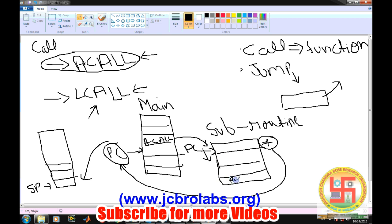And at the end there is a return instruction. In the return instruction, whatever address is stored on the stack is loaded back into the program counter, and now the program counter starts pointing to this particular address and executing instructions from there onwards. So it may be a little confusing to you, so let's repeat it again.